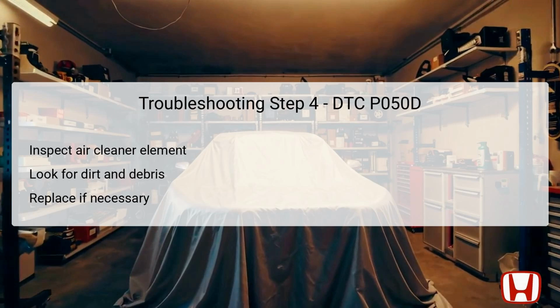This filter is responsible for trapping dirt and debris from the incoming air, ensuring only clean air enters the engine. Start by removing the air cleaner element and thoroughly inspect it for signs of dirt or blockage. If the element is found to be excessively dirty or clogged, replacing it is necessary to restore optimal airflow.